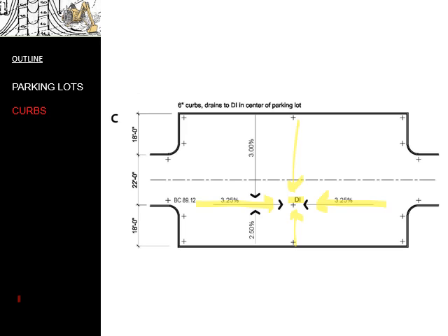But to begin with, you solve it in the exact same way. You know the starting point, the bottom of curb. You know the slope, so you can use that slope to find the next spot elevation. You know the slope running the other direction, so these two you can use to find this spot elevation.